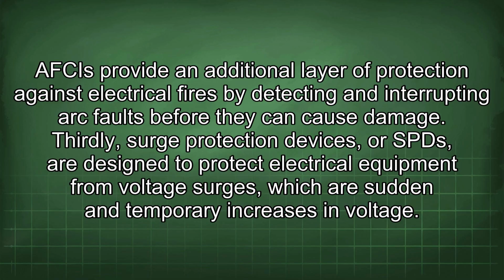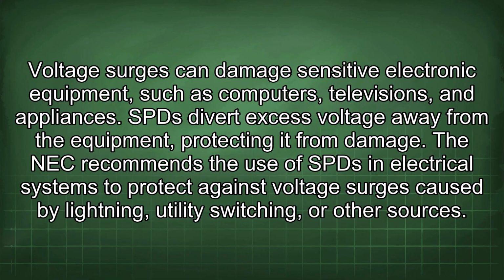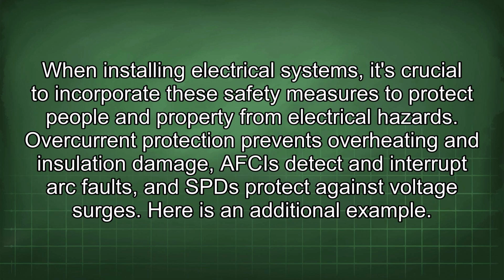Thirdly, surge protection devices, or SPDs, are designed to protect electrical equipment from voltage surges, which are sudden and temporary increases in voltage. Voltage surges can damage sensitive electronic equipment, such as computers, televisions, and appliances. SPDs divert excess voltage away from the equipment, protecting it from damage. The NEC recommends the use of SPDs in electrical systems to protect against voltage surges caused by lightning, utility switching, or other sources. When installing electrical systems, it's crucial to incorporate these safety measures to protect people and property from electrical hazards.